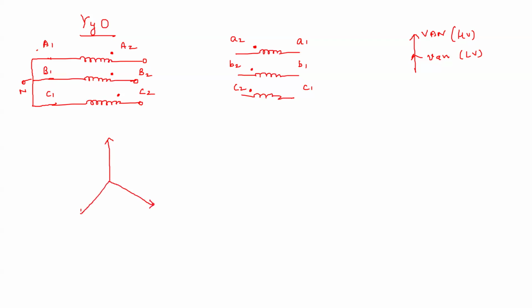I am drawing this exactly like how we draw in our three-phase systems. We have the phase sequence. Phase sequence A or R we draw here. Phase sequence B is 120 degrees lagging, so I am drawing it here. Phase sequence C is 240 degrees lagging with respect to A. As per the normal notation of the phase sequence, I have drawn this diagram.